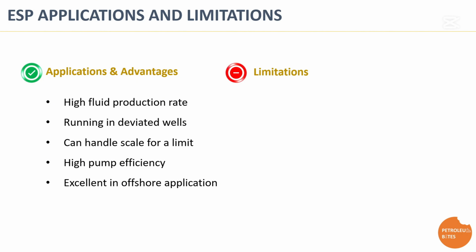Despite their many advantages, ESPs also have limitations that must be carefully considered during system design and operation. High gas-to-liquid ratio poses a significant challenge, as excessive free gas can lead to gas locking or a sharp decline in pump efficiency. Abrasive wear from produced sand also threatens ESP reliability, causing premature damage to critical components like impellers, diffusers, and bearings.